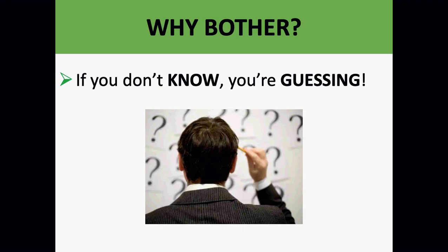It was one of our discussion board posts, I believe, on air quality. That house had a 2.5-ton system in it. My house has a 2.5-ton system in it. Big difference between house size. That system was grossly oversized and there's no way it would ever dehumidify. So again, if you don't know, you're guessing.